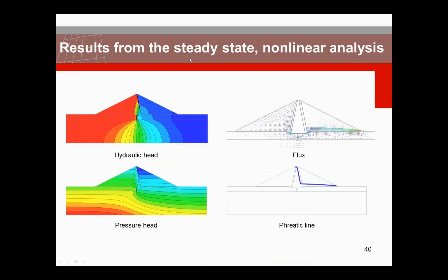So how does that work? We first do a potential flow analysis, or a groundwater flow analysis, in which we calculate the hydraulic heads, and then as a gradient, here you see there are some variations in color under the cut-off wall where the water flows under the dam, and also strong gradients here in the clay body where the permeability is relatively low.